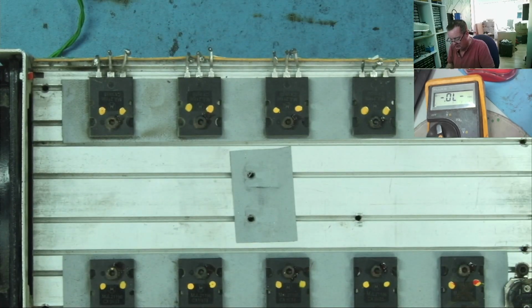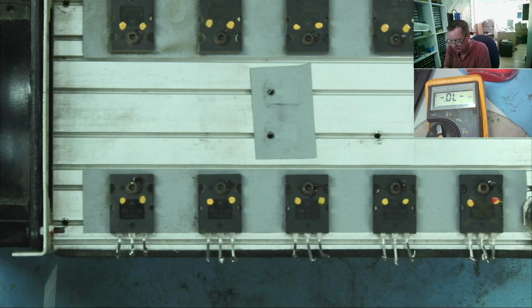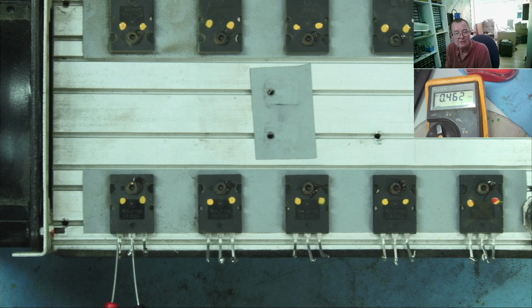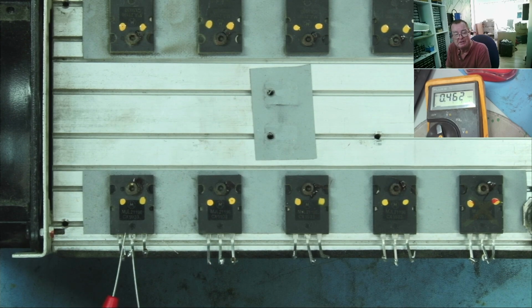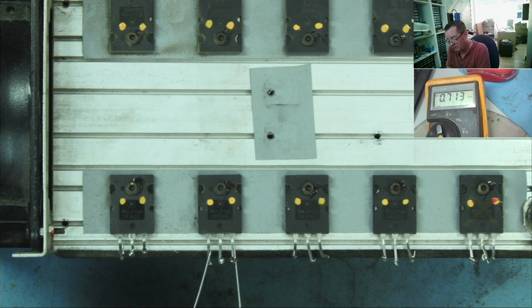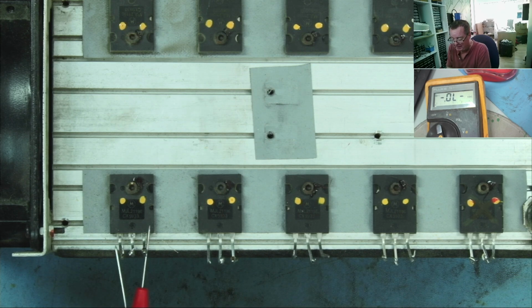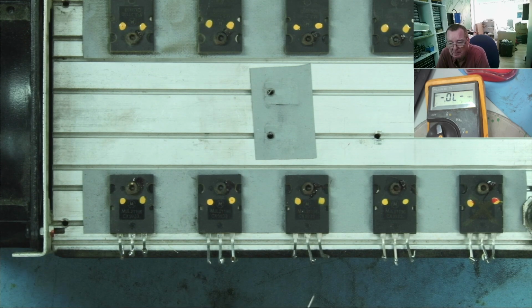I can flick it over actually, we just have some transistors here. This side's disconnected. So, same sort of thing. Base collector reads like a diode, and notice you're reading less than 0.5. These are large power transistors, that's not unusual. Base emitter, they're fine. Yeah, 0.489, 0.462. Notice also with these, we can tell which is the emitter. Higher reading. And we don't have that low resistance. So, base emitter, power output stages, expect there to be a low value resistance there.